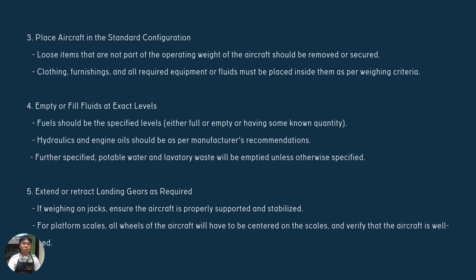Number 4 is empty or fill fluids at exact levels. Fuel, engine oil, and hydraulic fluids should be at the manufacturer's specified levels to avoid weight miscalculations. Followed by extend or retract landing gear as required. If using jacks, ensure the aircraft is properly supported. If using platform scales, on the other hand, all wheels should be centered for accurate readings.